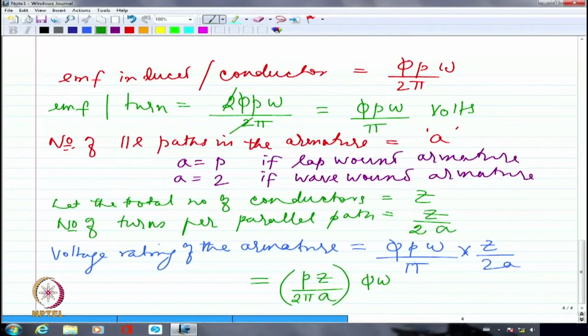Okay? So the speed is definitely under my control. In one sense, the excitation is also under my control. That's the reason I have taken them out, because they can be varied if I want to vary them. Right? So this particular constant of the machine generally is known as back EMF constant.